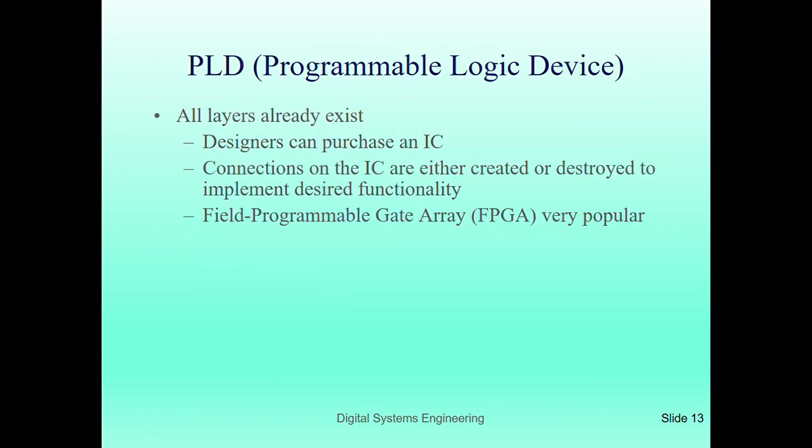Programmable logic devices. In programmable logic devices, all layers already exist. Designers can purchase an IC, and connections on the IC are either created or destroyed to implement the desired functionality. Here you can make your own connections, and you can also remove the previous connections. Field programmable gate arrays, FPGAs, are very popular in these kinds of devices.